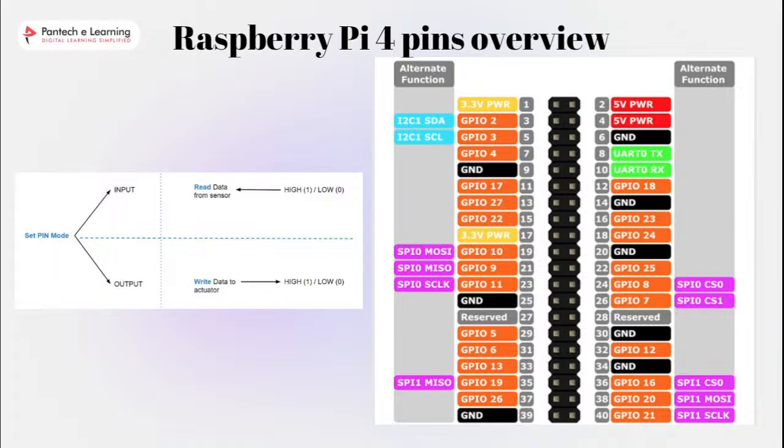High is 1 and low is 0. If you configure a GPIO as output, you will be able to write a value to it, also high or low, right? So a digital pin has only 2 states. Low usually means 0 volt and high usually means 3.3 volt, with some tolerance. That's very simple. It's like a switch that you turn on and off.